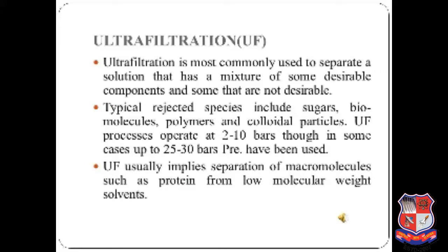The next advanced separation method is ultrafiltration. Ultrafiltration is a variety of membrane filtration in which hydrostatic pressure forces a liquid against a semi-permeable membrane. So normally ultrafiltration works on the principle of hydrostatic pressure force. In ultrafiltration, suspended solids and solutes of high molecular weight are retained, while water and low molecular weight solutes pass through the membrane.